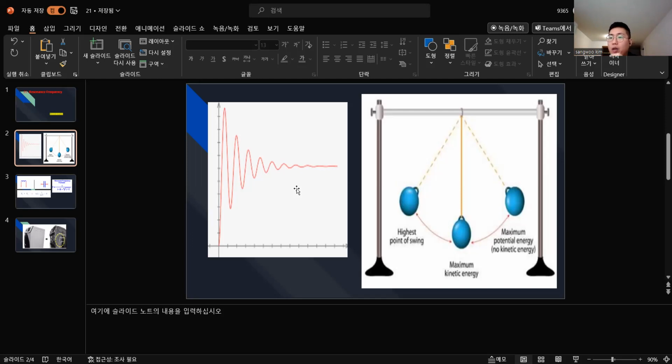Let's quickly review what makes a dielectric breakdown or insulation damage, which mean the same thing. It's called the three variable parts: voltage magnitude, voltage duration time, and voltage slope. Today's topic is frequency, the slope. Slope, as you know, is connected to frequency. But first of all, we need a quick review of the previous lecture. Let's move on.